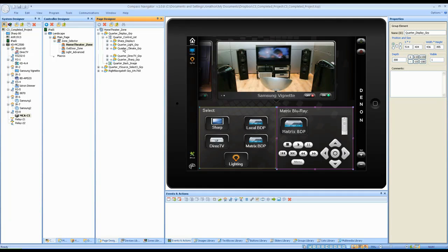Okay, and that climate control group, actually, we select it, we don't see it. Why is that? Because if I right-click that group, we have made that list position invisible. So you could see here it is invisible. We could also see in the properties on the right-hand side it's invisible. When you make a list position invisible, what does that do? It just hops from, say, if this is list position 3, which it is, it hops from 2 to 4 as you navigate through your list, or from 4 to 2 if you're navigating from right to left instead of left to right. And that can be very useful.